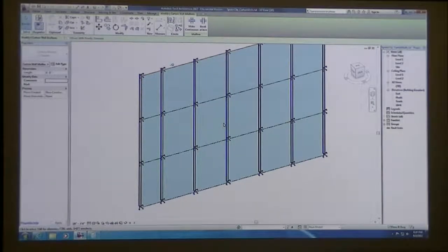But the reason I haven't gone over how to do the column grid spacing yet is because, as an architect in the office, 9 times out of 10 you are going to be giving the structural engineer the column grid spacing for them to begin designing the structure. The reason for that is typically you want to come up with a module. In this case, we have a very repetitive floor plan, or at least a floor room unit, a typical guest room in a townhome loft, or not a loft, but a 2-bedroom timeshare unit. As those lay out, you've developed some kind of design for what that room needs to be, and then you're laying them out on a particular module.